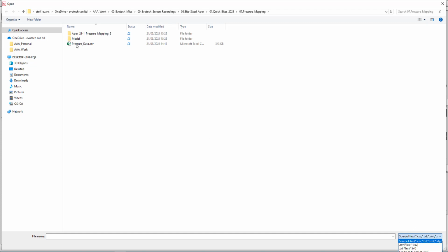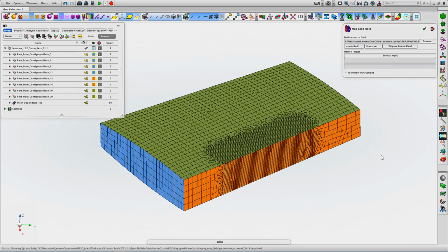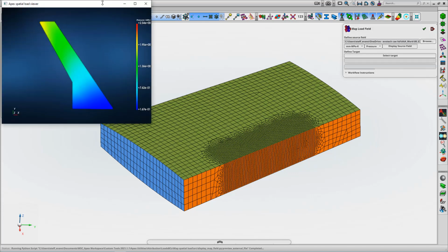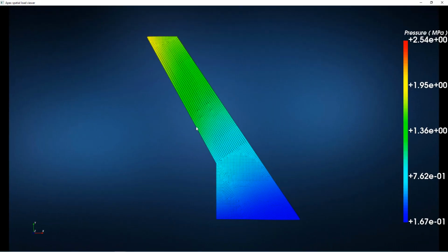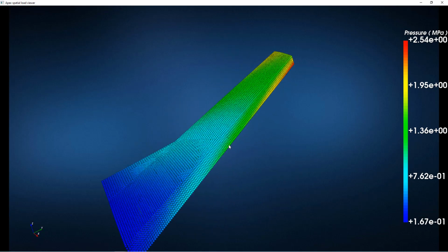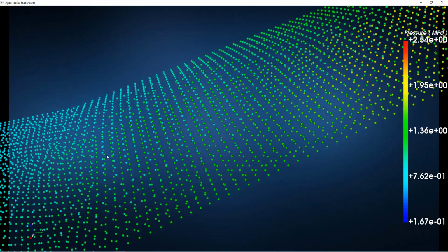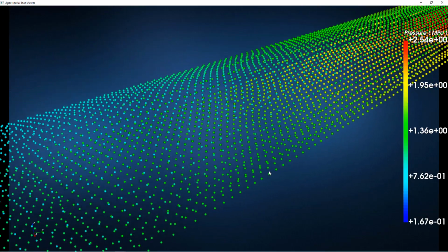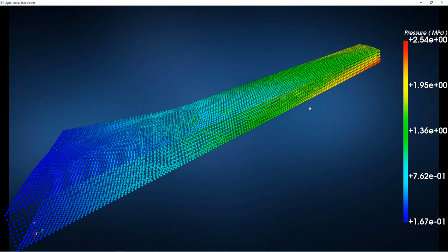I'm going to pull in a pressure map, which is effectively an XYZ scalar plot against position. So specify the units we're bringing in, specify whether we're bringing in a pressure or a temperature, and then we can visualize the source data. This is the pressure field that we've got. It's a pretty unique way of visualizing things. Here, like I say, we've got this XYZ definition and the associated pressures, with a fringe plot shown for the appropriate units.